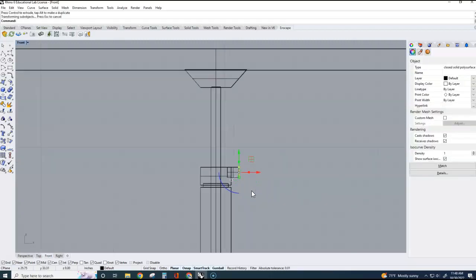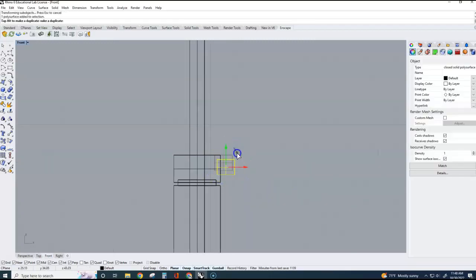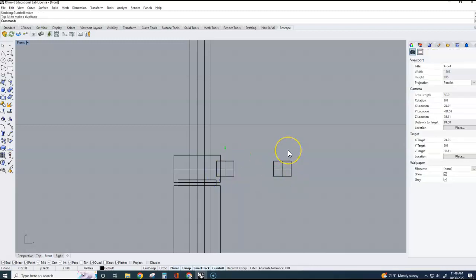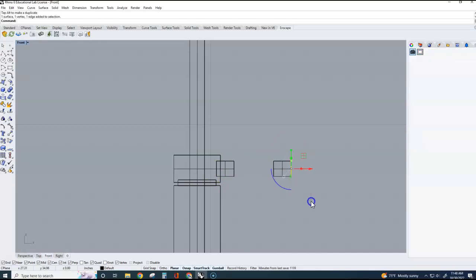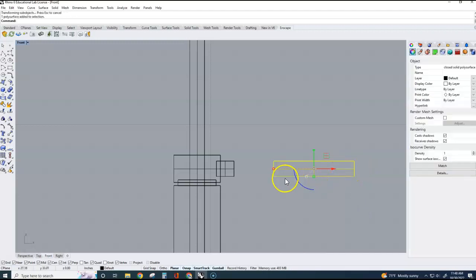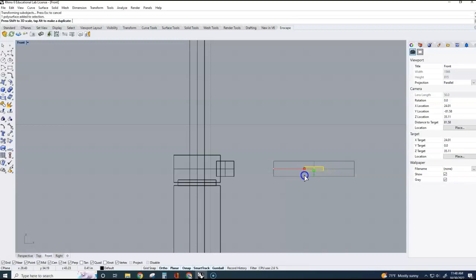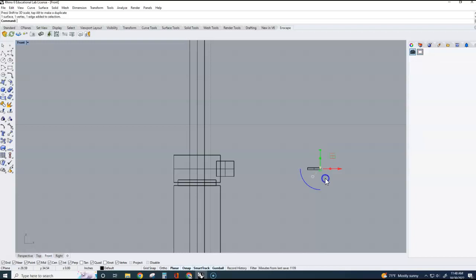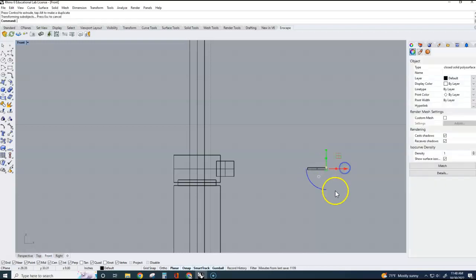So I'm now kind of going into my advanced editing mode here. I'm going to make a copy, Alt and drag. Hold down Control and Shift and drag over that face so I can stretch it out. Oh yeah, I do have scaling capability here, which is great. So I'm going to make it a little skinnier for that little handle. Control Shift again, just to make that handle a little longer.